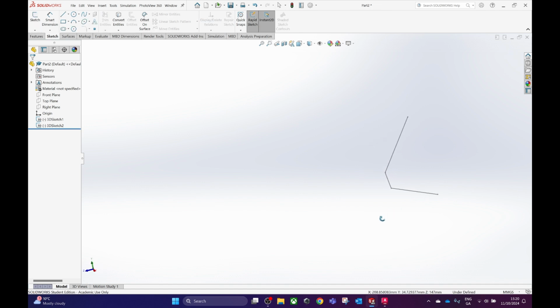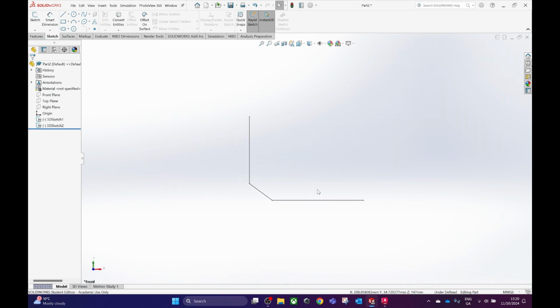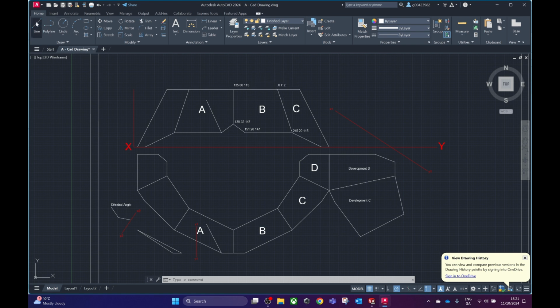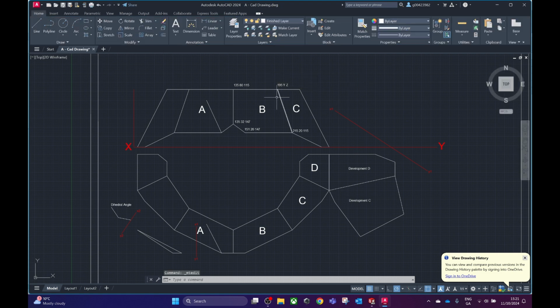So now you can see we do have a 3D sketch and it's starting to resemble that surface. So let's pop it back in here. We just need one more point and then we can connect it in. So let's pop back into here last time. Draw our line over to the line. So x is 195. Our y coordinate is going to be 80.